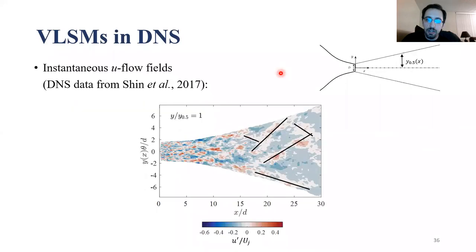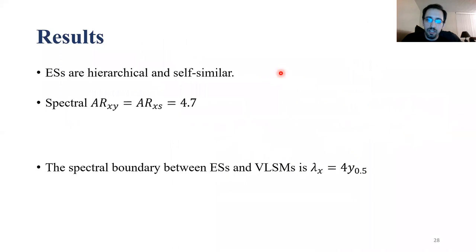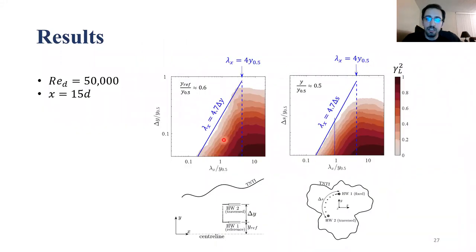The linear coherence spectrogram doesn't look like this. We don't have these nice isocontours that are parallel to a constant line. You can probably imagine, because we have these dominant Kelvin-Helmholtz eddies, circular eddies that dominate the other structures. So that eddy dominates these coherence spectrograms as well.